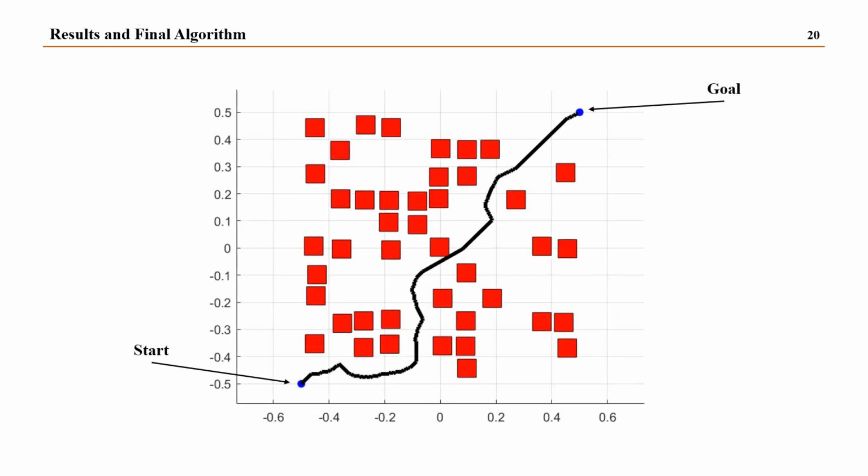So this right here shows the path that we were able to find using the harmonic potential field path planning. You can see that the robot can easily navigate here in a kind of smooth path. Now here it seems to have been stuck in a local minima and was just able to find a straight line leading to a point with a lower potential and better characteristics. And again, it might have been stuck around here, another straight line, and probably here, another straight line, and then just glided towards the goal. Now, this local search idea works just fine until we get to a neighborhood of the goal, in which we are kind of ensured that we will be able to reach the goal safely.